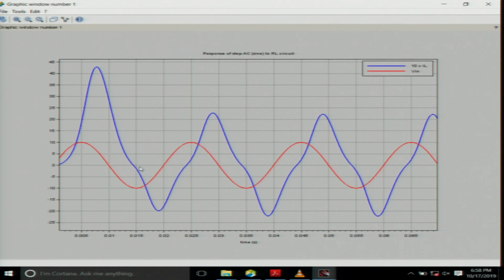So, you find a kind of peaky nature, a peak which you get somewhere, because you need much more current to set up the same amount of flux because of the nonlinearity. Okay. So, this is an interesting aspect about a nonlinear core. In steady state you get a non-sinusoidal waveform. It has got harmonics, although it is periodic, it is not sinusoidal, and the current is of a very peaky nature.